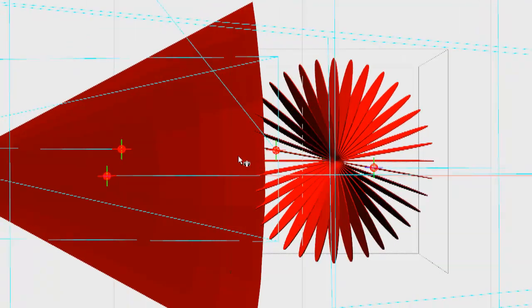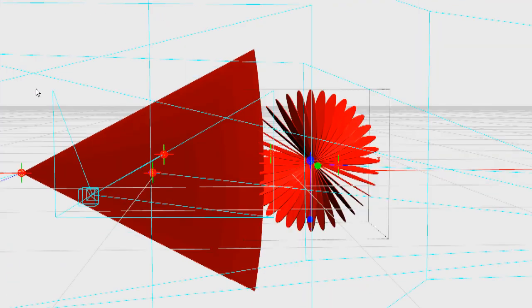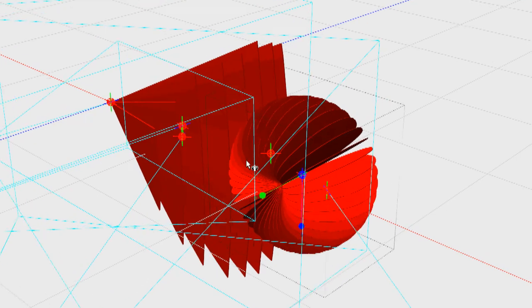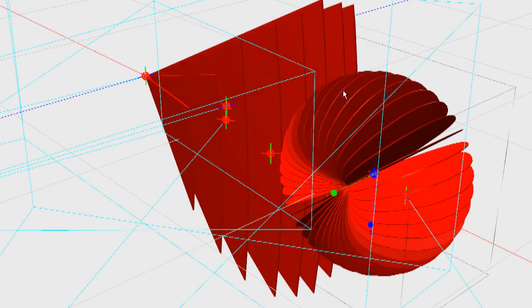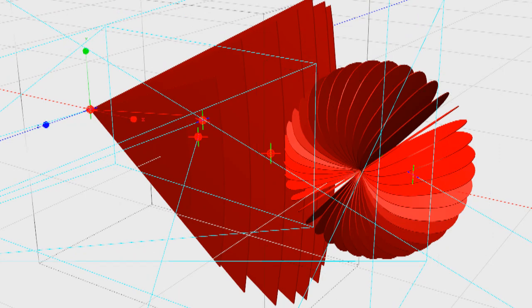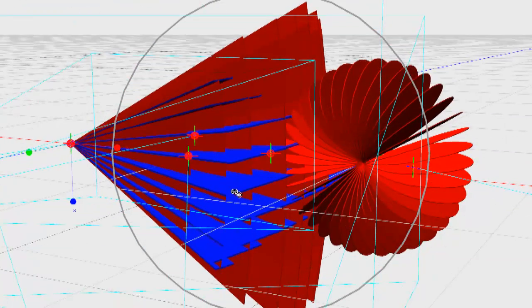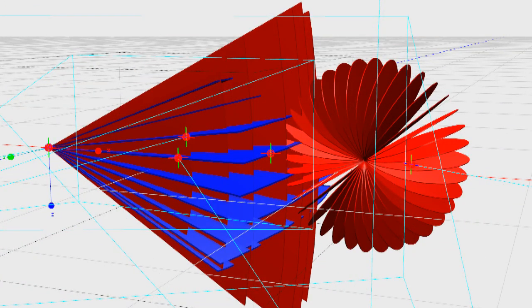of polarization. However, because it's a diversity antenna, not only does it have the vertically polarized antenna built in, but there is also a horizontally polarized antenna. It's exactly the same as the vertical one, it's just mounted at 90 degrees.